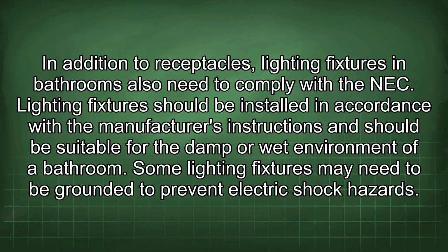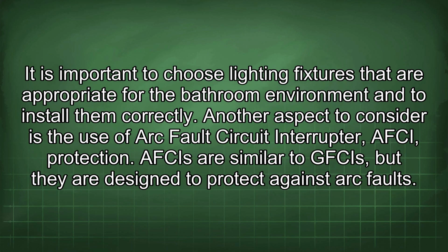In addition to receptacles, lighting fixtures in bathrooms also need to comply with the NEC. Lighting fixtures should be installed in accordance with the manufacturer's instructions and should be suitable for the damp or wet environment of a bathroom. Some lighting fixtures may need to be grounded to prevent electric shock hazards. It is important to choose lighting fixtures that are appropriate for the bathroom environment and to install them correctly.